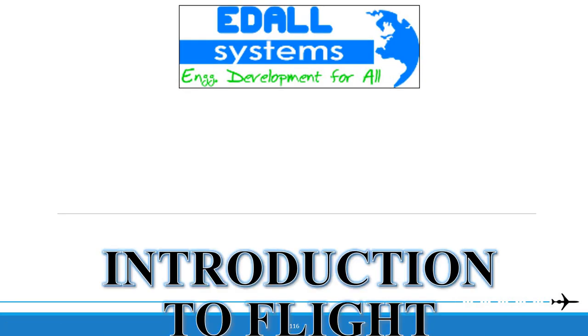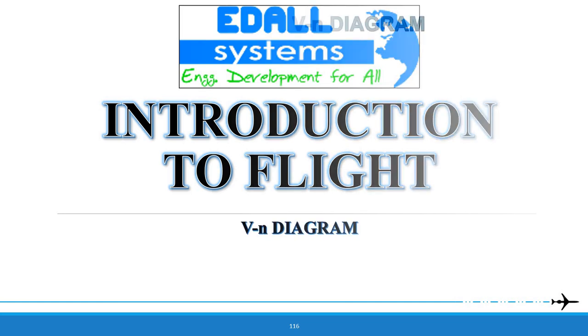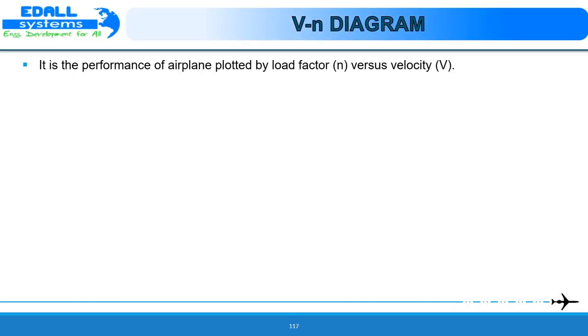In our previous session, we had seen turning flight. Let us move on to the Vn diagram in this session. The operating flight strength of an aeroplane is represented in the form of a Vg or Vn diagram, where V denotes airspeed and g or the n denotes the load factor.